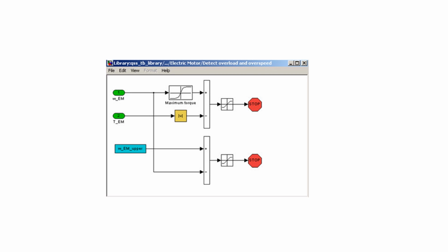Using these Simulink model blocks is fairly straightforward, but take special care to check the max electric machine power demand and the maximum machine speed are not exceeded. With the basic principles covered here, you should be ready to use QSS to explore some of the electric powertrain design space for road vehicles.